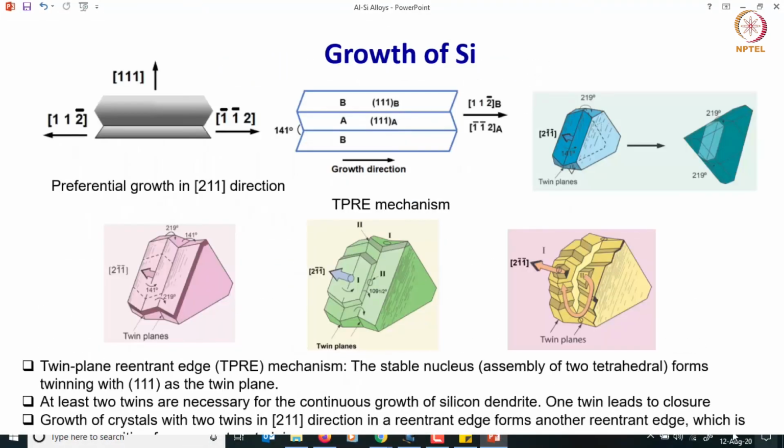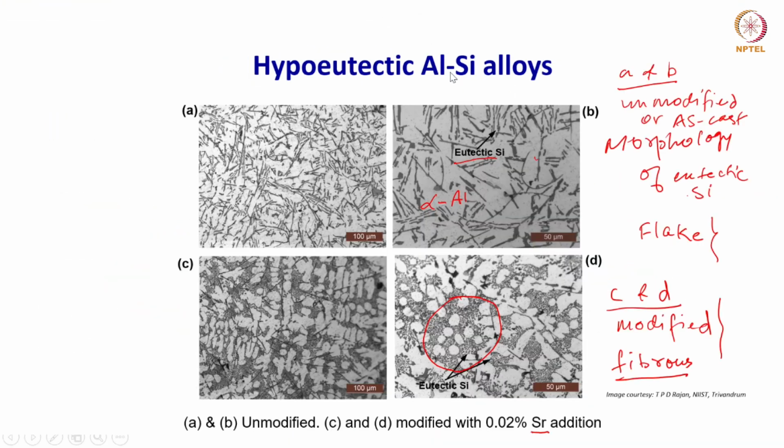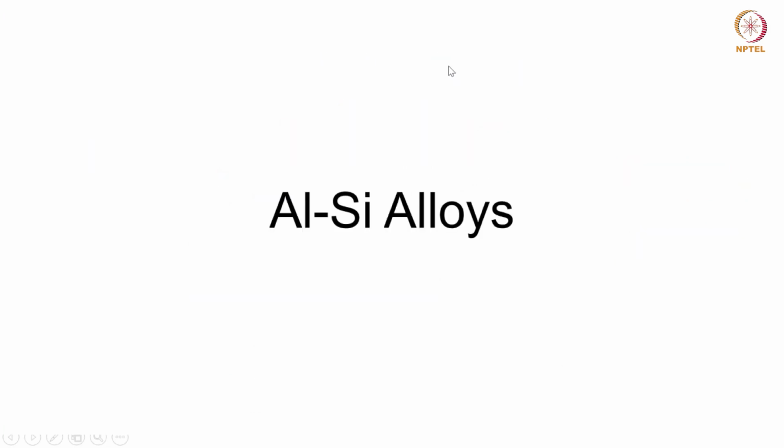So before we wind up, let us have a look at what we have learned today and take a summary. We primarily talked about the cast alloys, and we also understood the different designations of cast alloy. Here, unlike the wrought alloys, we have 3 digits to specify that designation, like 1XX, 2XX, and so on. Apart from that, you may also have a decimal point and a digit followed by that.